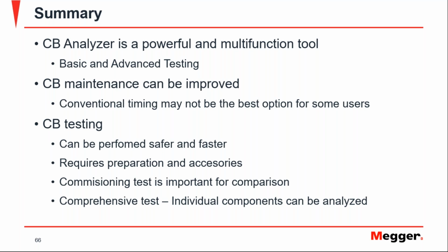And well, the important thing is to be prepared, to know what you want to do. Once the breaker fleet is the same for a particular company, you know what accessories you need, and especially for the travel measurement, you can define that in advance, and that won't be a problem anymore.